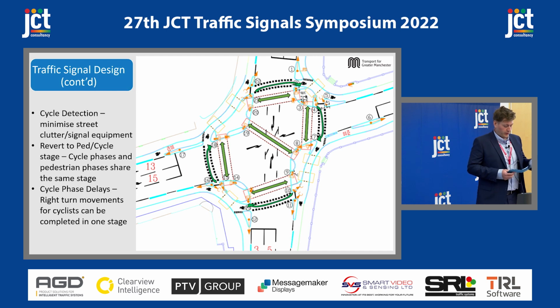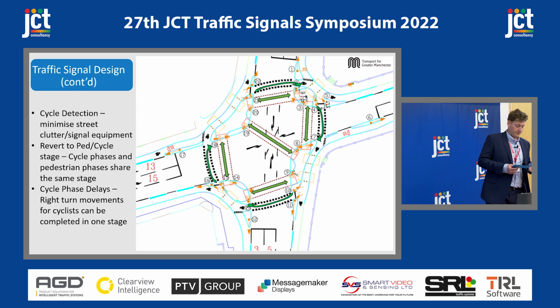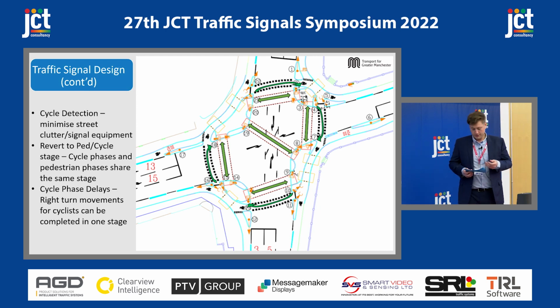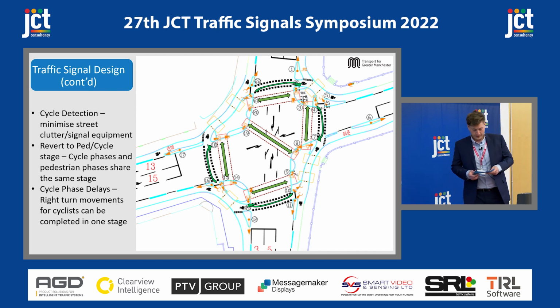Also, you can revert to pedestrian and cycle stage. So at a traditional junction where cyclists share the same phases as general traffic, cyclists will be disadvantaged if the junction reverts to an all red or full pedestrian stage. So with the pedestrian and cycle phases sharing the same stage in CYCLOPS arrangements, the CYCLOPS design becomes an ideal candidate for reverting back to an all red or full ped cycle stage.